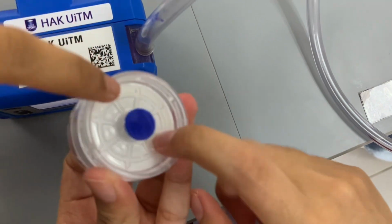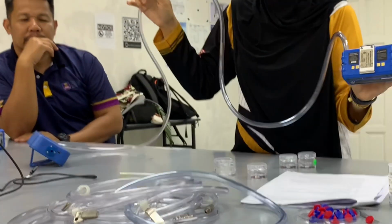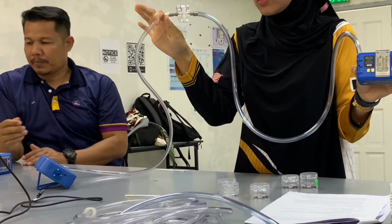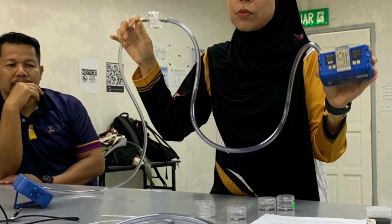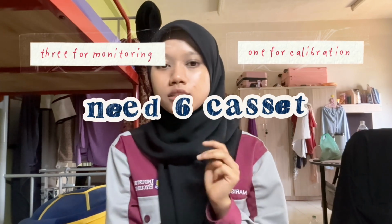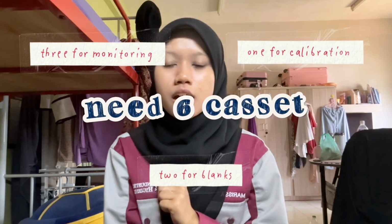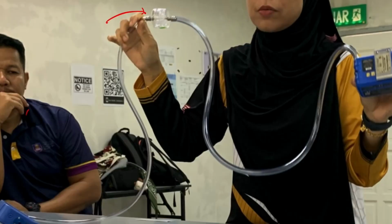Each cassette has two sides, which are the inlet and outlet. The inlet is where air enters the cassette and the outlet is connected to the pump using the connecting tube so that air can be pulled through the filter. Before sampling, we prepare a total of 6 cassettes. One cassette is used for calibration, 3 cassettes are used for actual sampling, and the 2 other cassettes are used as blank samples.